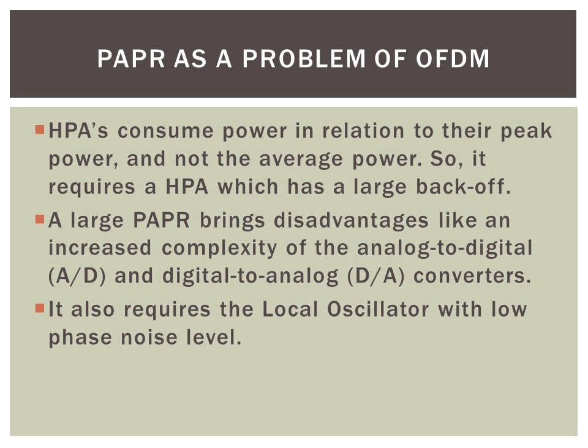In that case the local oscillator plays an important role, but as we are merging the different signals, there may be chances of adding phase noise. That phase noise should be avoided, so we require a very low phase noise level in the local oscillator.